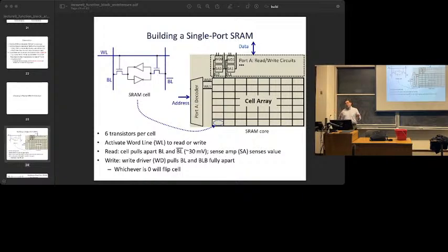If you actually make what's called an asynchronous SRAM, you have to detect when the addresses change and then basically start all those timers. That's kind of a real pain to make a bunch of circuitry just to figure this out. So maybe 20 or 25 years ago, people just went, we're not doing this anymore. You give us a clock. Does that answer your question? So all of these SRAM blocks that I'm showing you are synchronous.